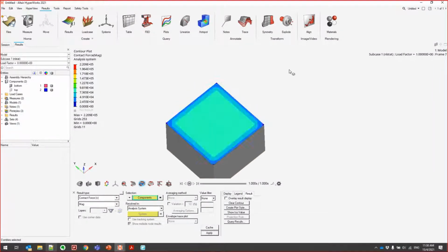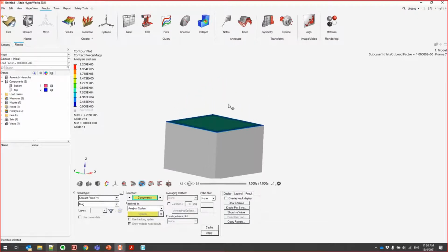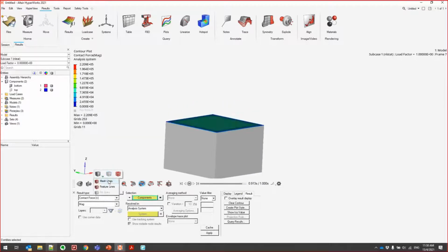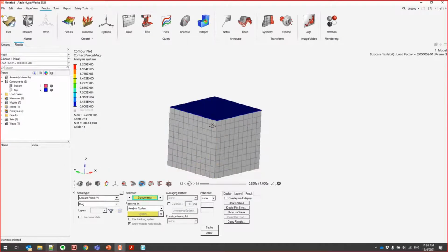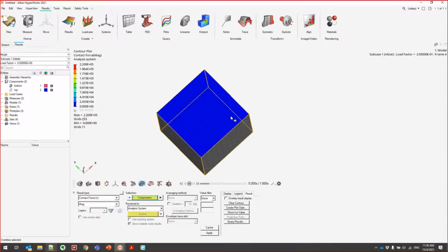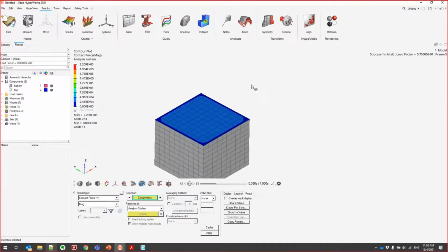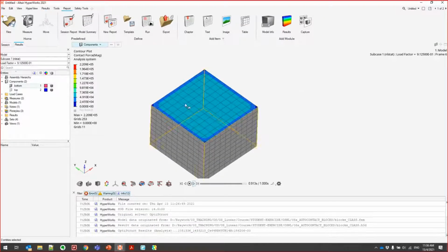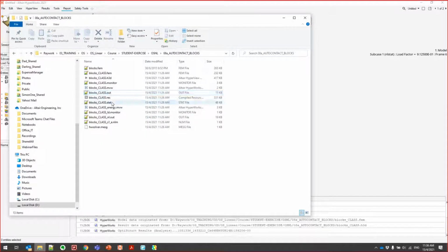Now this is surface to surface. If the smaller mesh size is going to be slave, right? So this is like the ideal condition. Okay, yep, so that's the best case scenario where we have smaller mesh size as slave, and then it's surface to surface, right?